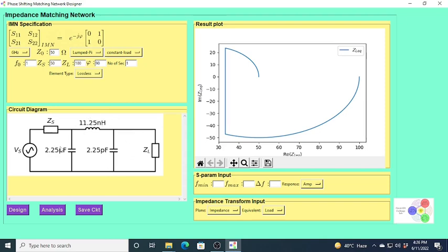Now this is the design, or the circuit. As we know, it is equivalent to a symmetric quarter wave length transmission line of characteristic impedance 70.7 ohm, and quarter wave length means a 90 degree transmission line. So this is equivalent. Now, what is happening here? There are two phenomena occurring here.